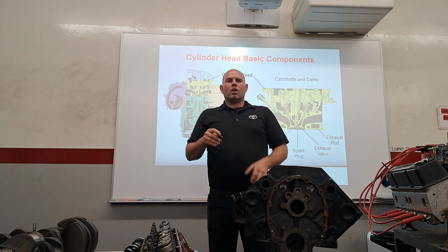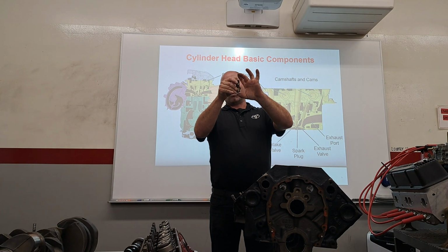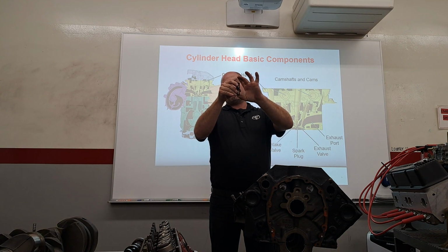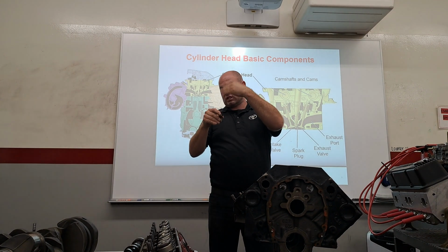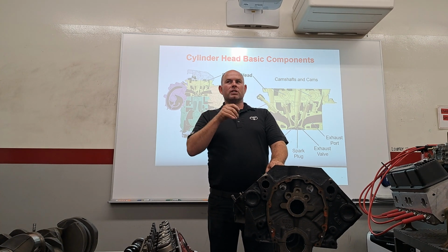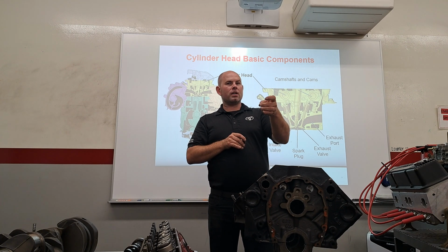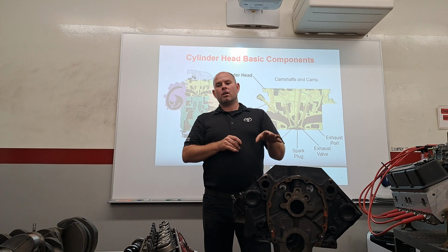Whereas before lifters, there was none of that. There was just a flat tappet roller, or even just flat tappet. It wouldn't even roll, it would slide across the cam. Those would need adjustment. 2JZ, for example, there is no lifter. There's just the cam on a bucket. That needs to be adjusted. Should it change much? Not really.